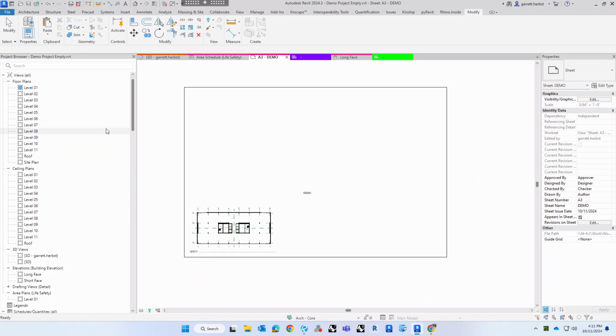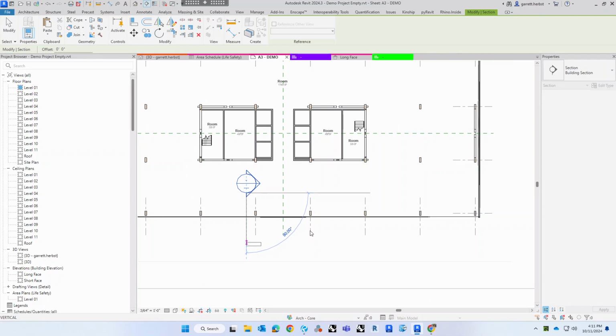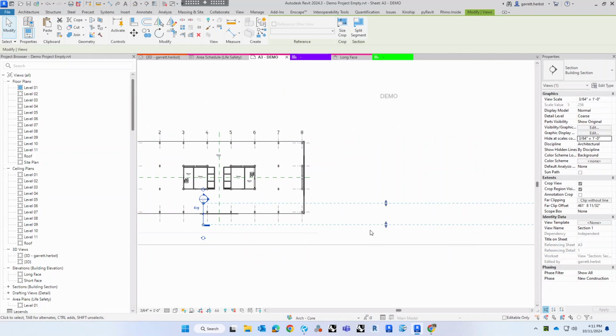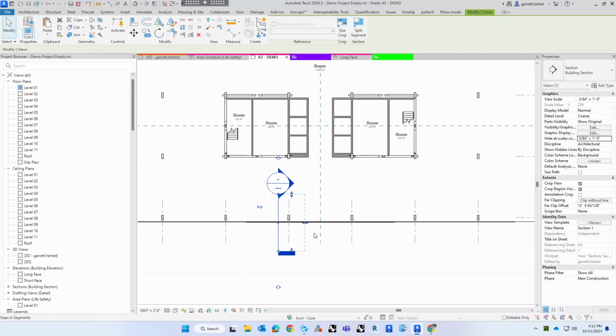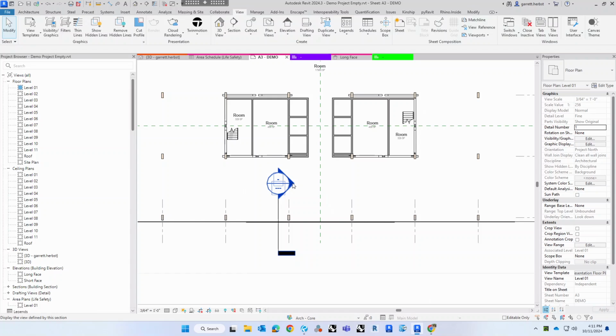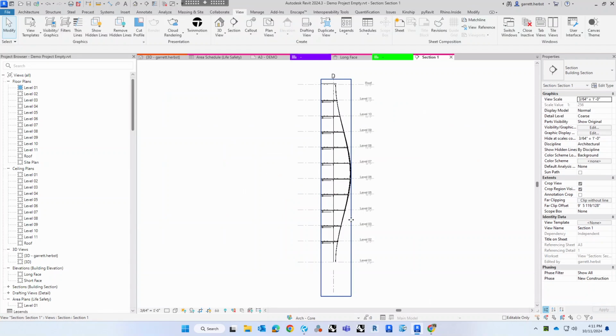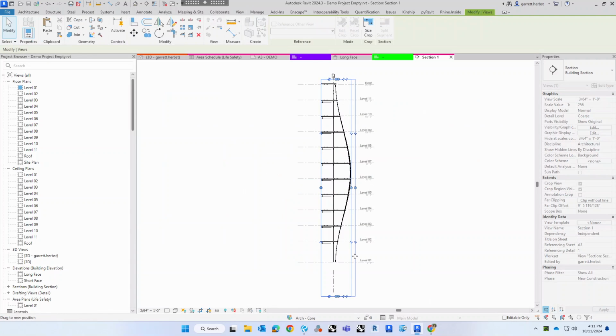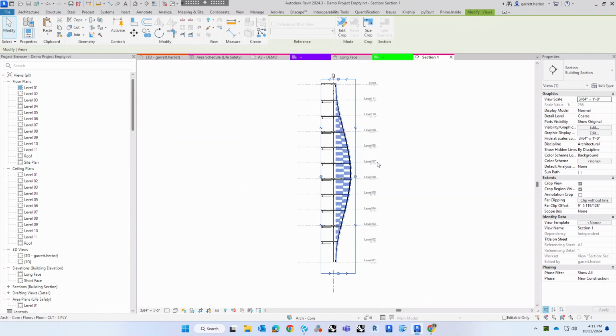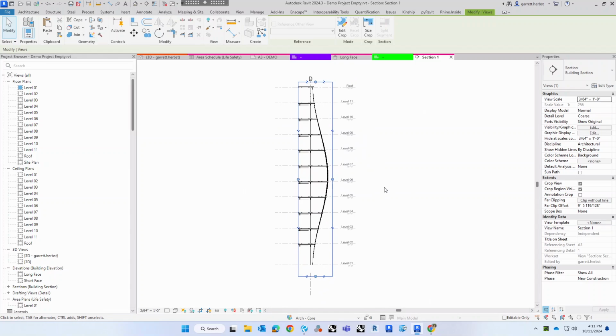So sections. So you're going to have to be doing a wall section. Everybody should know how to do sections. And again, you can make sections as pretty as you want. When you're building sections, make sure that you're setting the extents of these sections correctly. So not only depth, right? So you either do or don't want to capture a certain amount of distance away from the cut line, as well as how far, right?